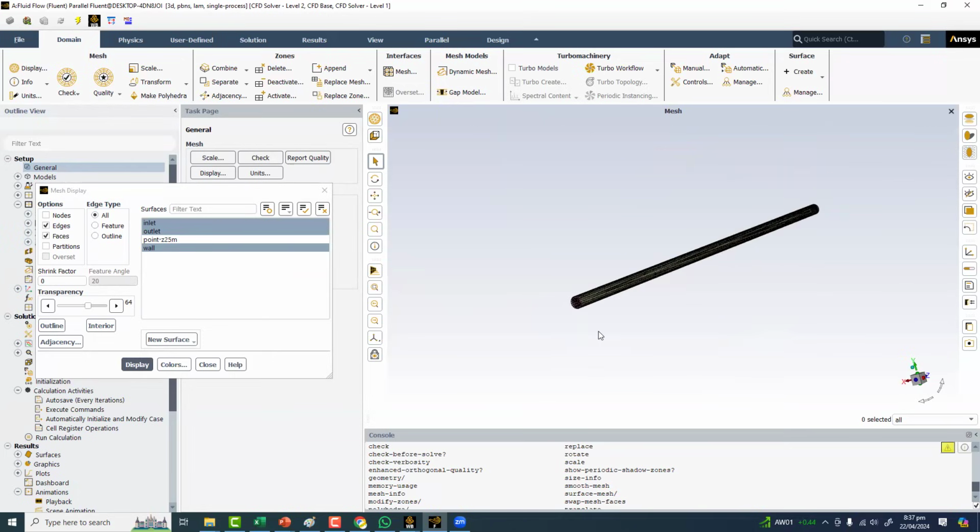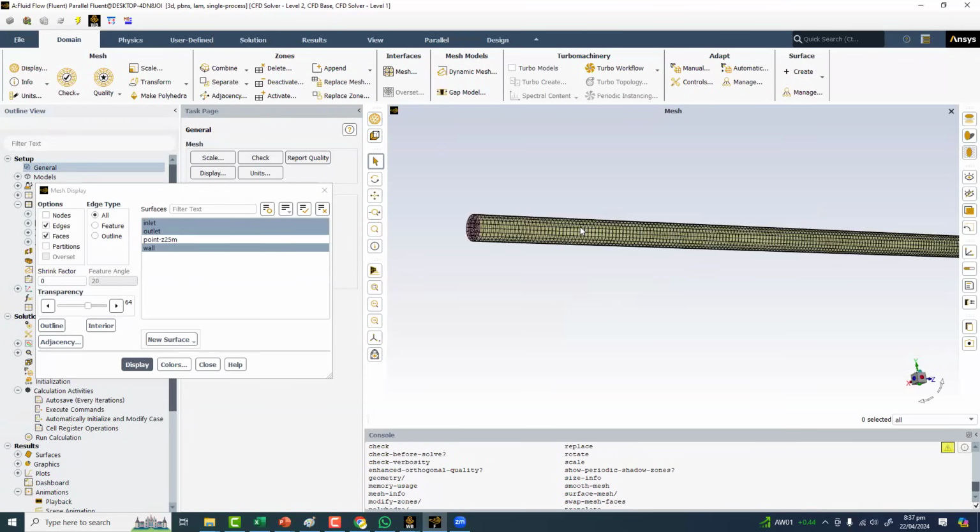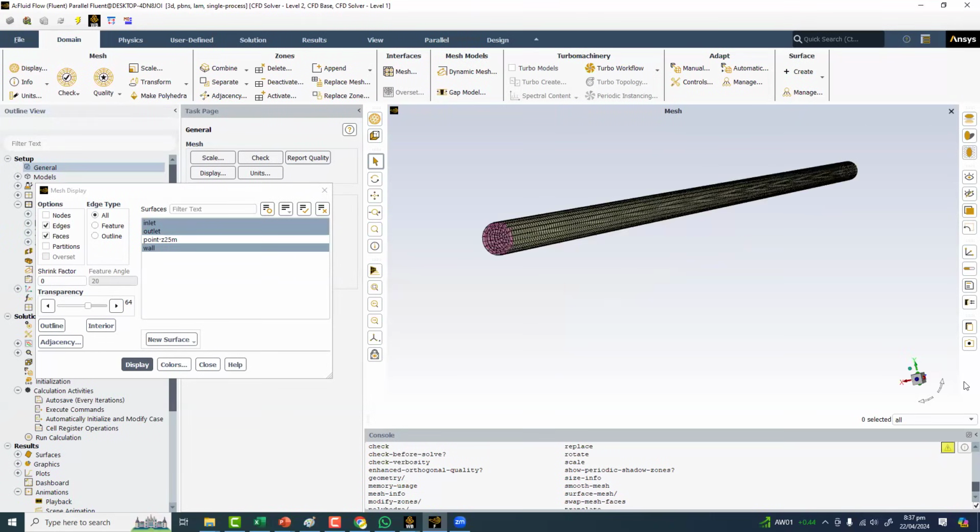Actually, at the moment, this pipe has no orientation definition. Right now, its inlet and outlet are along the Z axis, so we are going to provide the flow along this dimension. At the moment, we are not putting any gravity effects there, so there will be no body force here. So putting it in any orientation will not make any difference to the flow solution we are going to get.